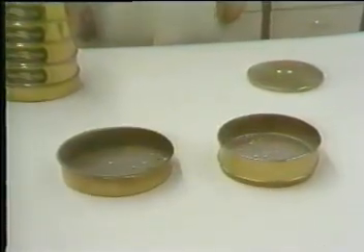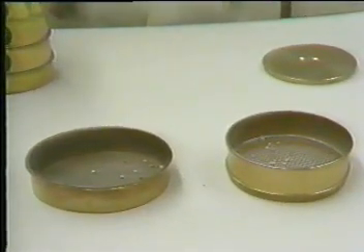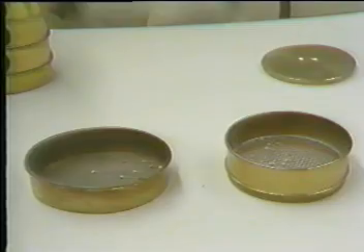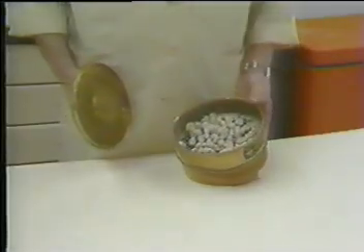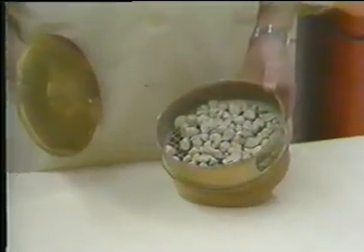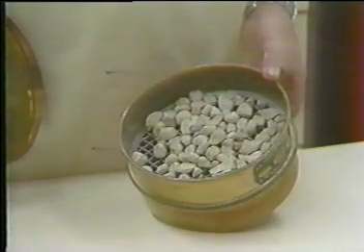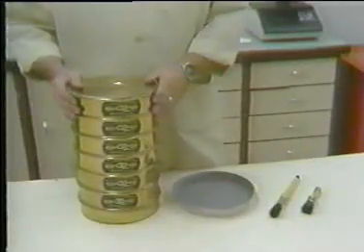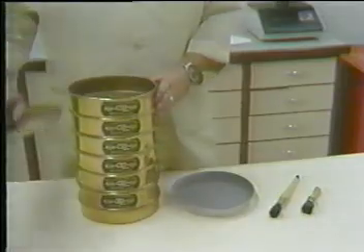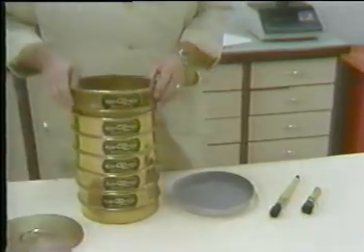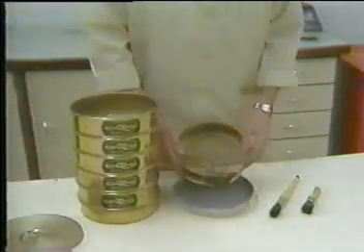If, after 1 minute of hand sieving, the amount of material passing the individual sieve exceeds 1%, the period of agitation was not sufficient. In determining the sufficiency of sieving for sizes larger than the number 4, limit the material on the sieve to a single layer of particles. Once the sample has been agitated sufficiently, determine the weight of the particles retained on each sieve size by weighing on a scale or balance.